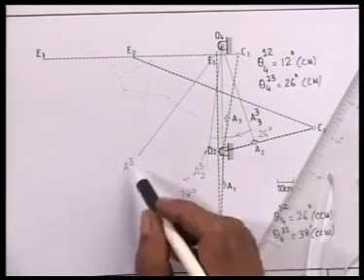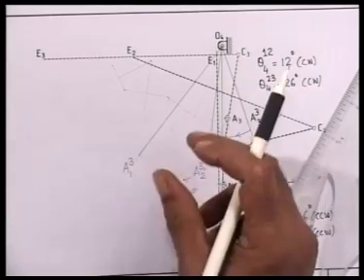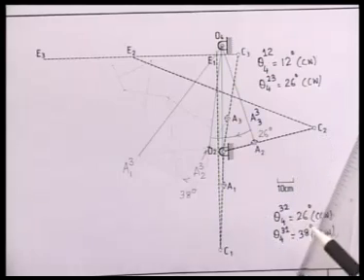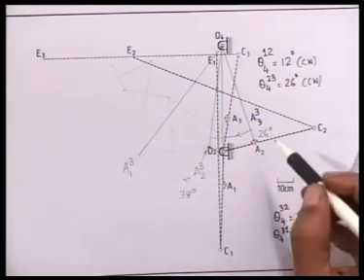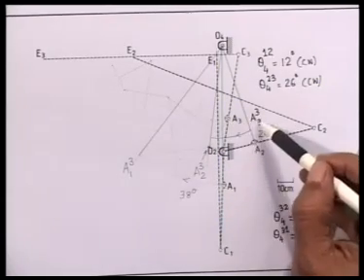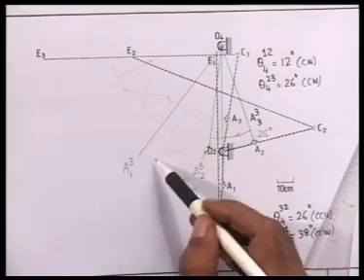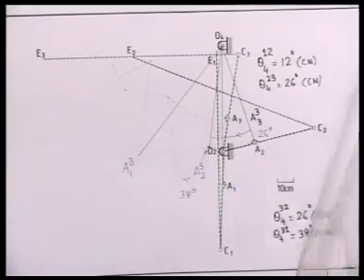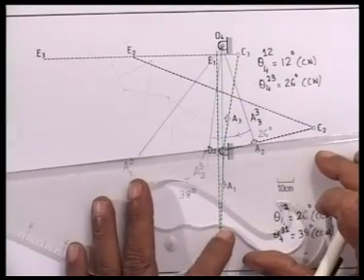Because it is inverted on the third position of O4B, and the rigid link AB is of constant length, the center of the circle passing through these three inverted positions, namely A3, which is A33, A23, which is here, and A13, is B3. So we determine the center of the circle passing through these 3 points in the usual manner.